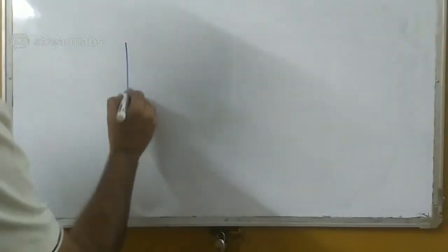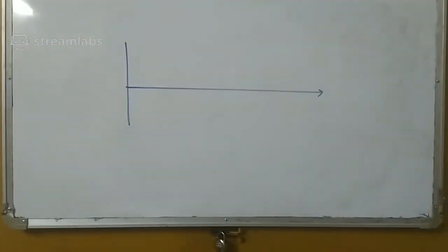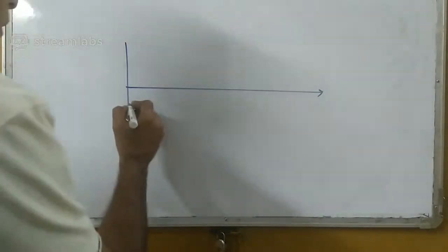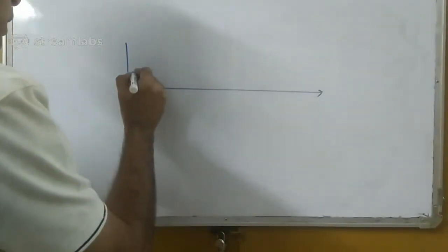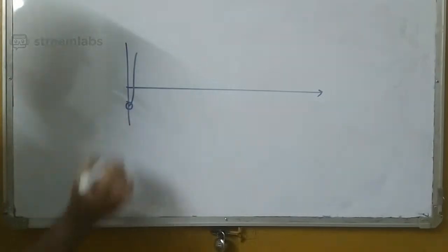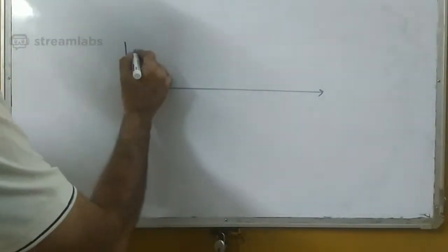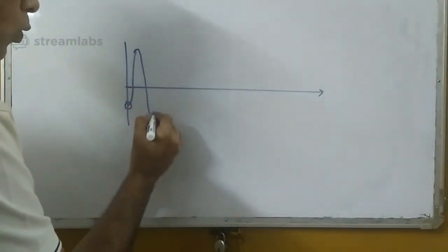So your carrier and your bit stream I am not going to change. At the beginning I start with 2 bits at a time. First I am going to start with a signal with minus 135 degrees. I'll assume that minus 135 is this particular phase, which is meant for representation of 2 bits.